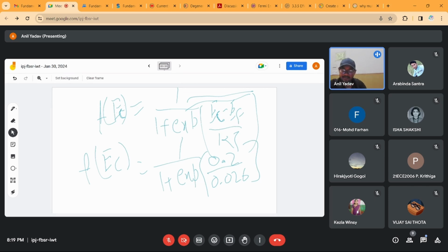So different lithography techniques will do that job. Electron beam lithography goes in the nanometer. Then again comes UV lithography, deep UV lithography. With UV lithography we can write the pattern; I have done it till 5 micron, 2 micron. Till 2 micron I myself have done. My lab mates have done till 50 nanometers.